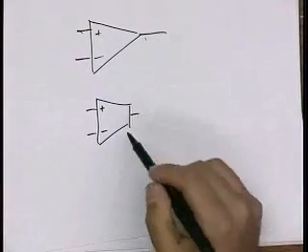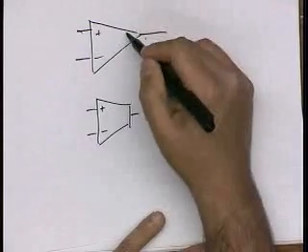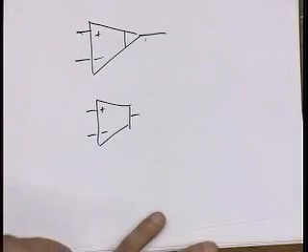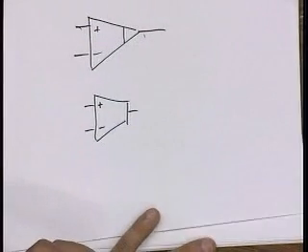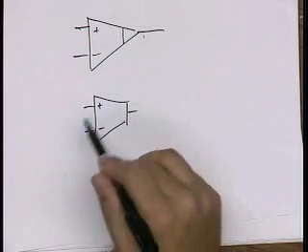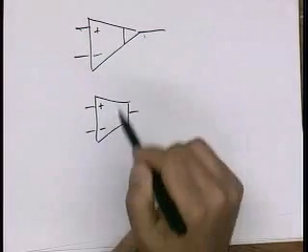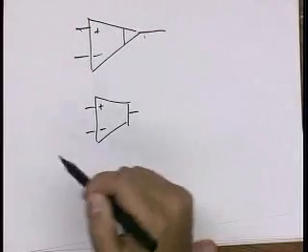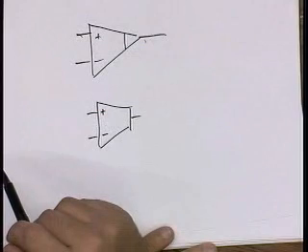Okay. Well, what about this poor OTA? It looks like it's a chopped off version of this device, right? So we chop off the end triangle and we end up with an OTA. Now, when I first saw this symbol, I thought, okay, someone was just trying to distinguish an op-amp from an OTA, because a lot of times people don't. They just draw OTAs like this. That can lead to confusion.